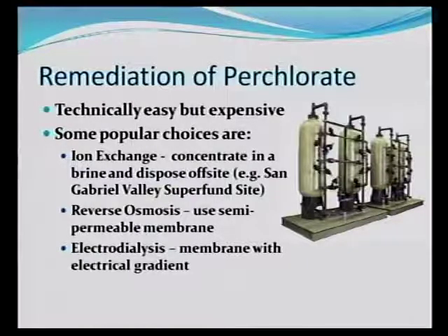And I wanted to make some mention of perchlorate. We talked about perchlorate transport a little bit last time. We said that it was a salt, dissolves in water, so we don't have any of this immiscible phase to deal with. So, the downside of that is it transports fairly quickly. The good thing is that if you pump it out, you can pull it out with the water. Generally, it's not so hard to pull out. And then once you have the water, you can treat it. And because it's a salt, it can be treated by ion exchange.